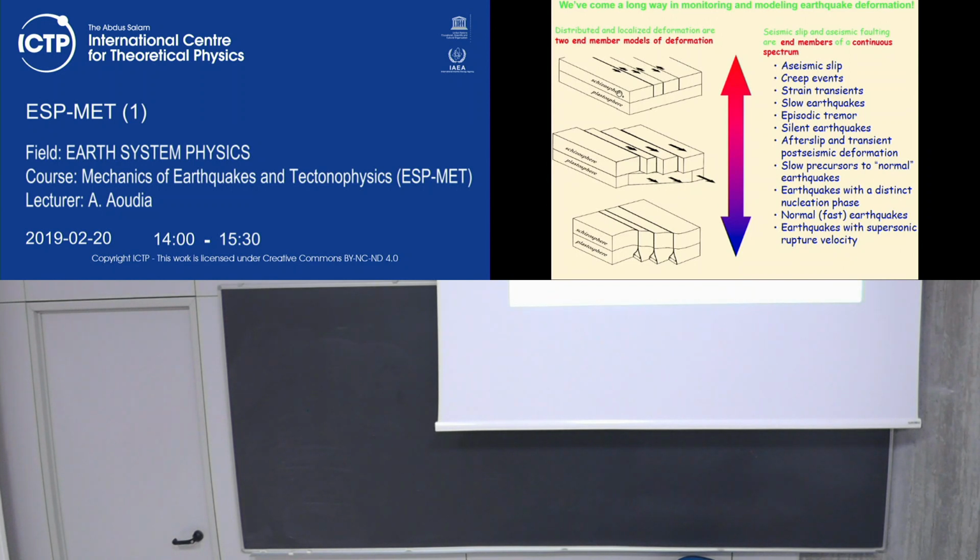What is the difference between a seismic slip velocity during an earthquake and the rupture velocity? Tom? Rupture is a kilometer per second. Right, and the seismic slip velocity is? Is a centimeter per second. That's great. Yes, this is meters, centimeters per second. This is really the displacement that you have on the fault, right? When we talk about rupture velocity, we're talking about the rupture front that we get from the seismic waves.